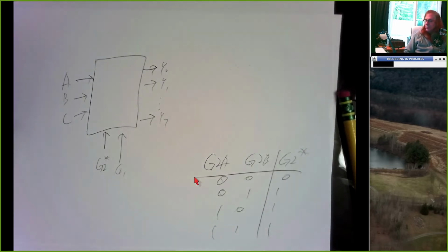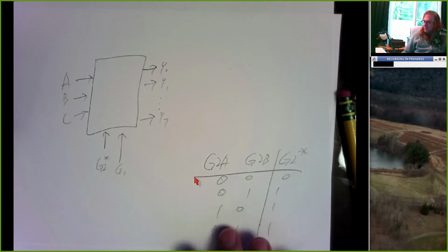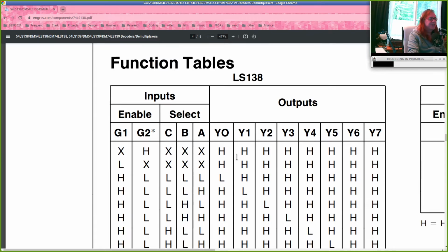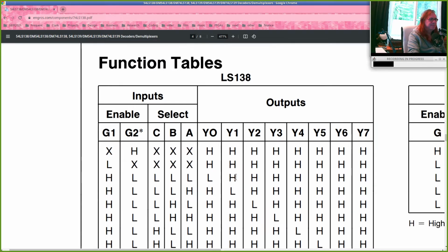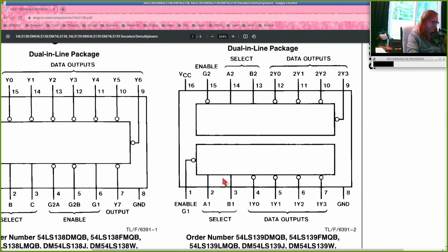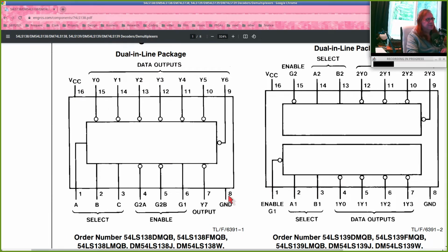It tells us that it's an OR of these two inputs, and so if either of those inputs is high, G2 star is high. And if G2 star is high, then all of these outputs are driven high. So if you go back and look at the actual pins on the chip, there's your power and ground connections as usual. Here are 7 of your outputs, Y0 through Y6. Here's your 7th output. Here are your selects A, B, C. But here are the enable inputs, G1, but then G2B and G2A. And so to enable this device to work, G2 star has to be 0, which means both of these inputs...